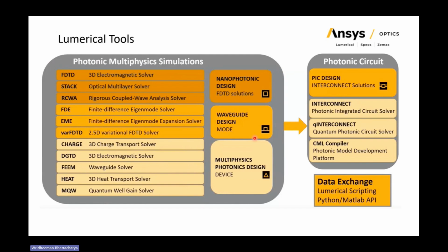All the built-in modules are there, and if we want to build, suppose, a waveguide with a different effective index or group velocity, or an electro-optic modulator with our own doping levels, then we can build it separately in the multiphysics devices and FDTD, and then import it into INTERCONNECT to see the effect at a whole system level.